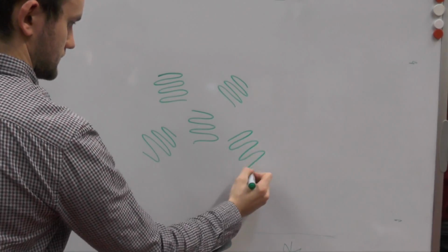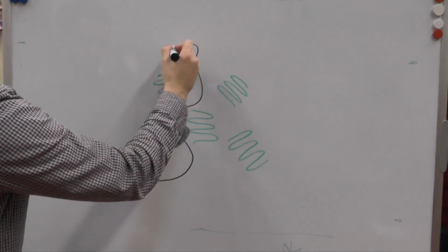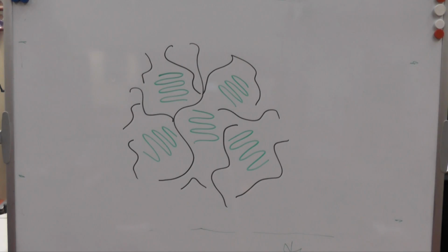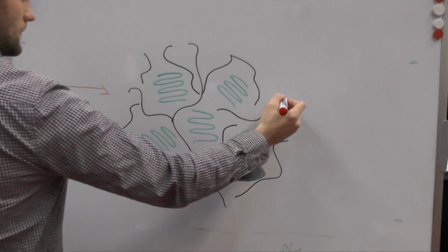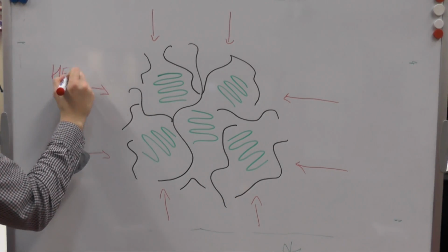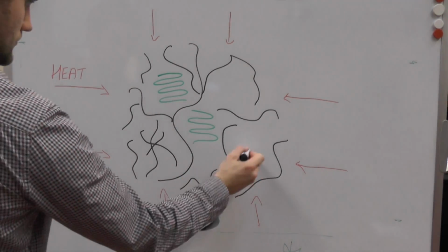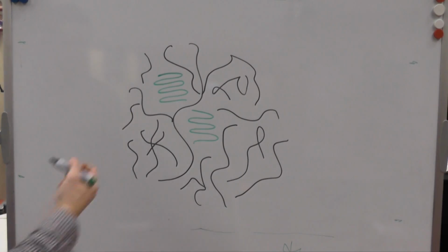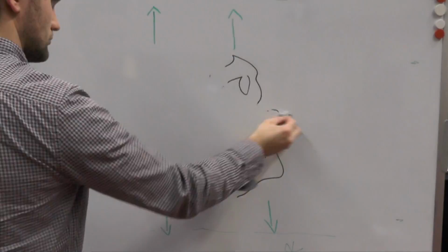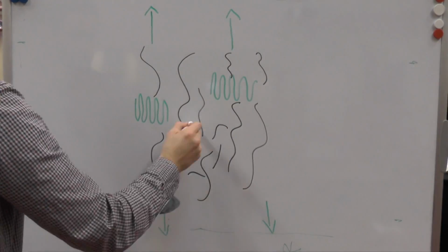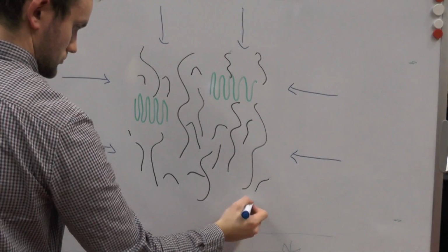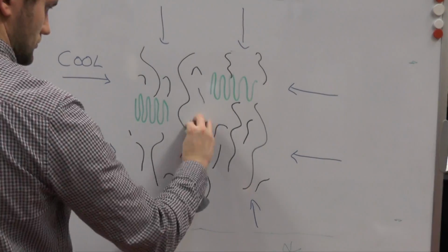Semi-crystalline polymers have regions where the molecular chains are ordered, known as crystals, and regions where the chains have no order, known as amorphous regions. This structure is dependent upon the thermal and strain histories applied, because when you heat the sample, you give the chains energy to break free from the crystal structure. Then, when you stretch the sample, you cause the chains to align in the stretching direction. And finally, when you cool the sample, you allow more crystals to form.